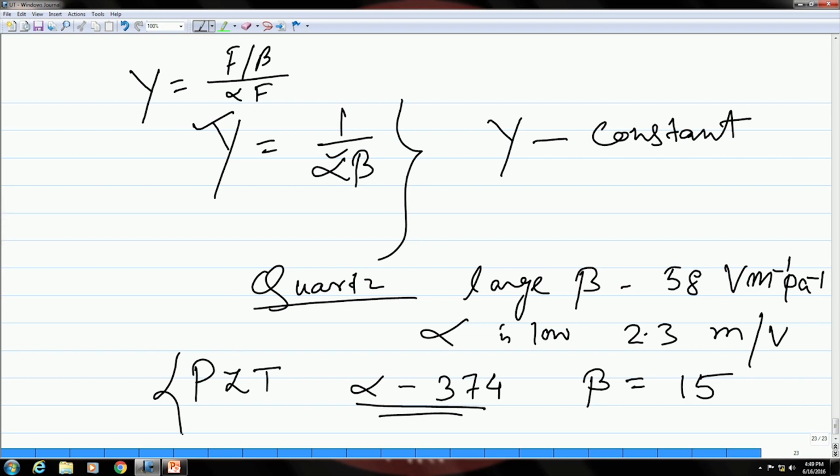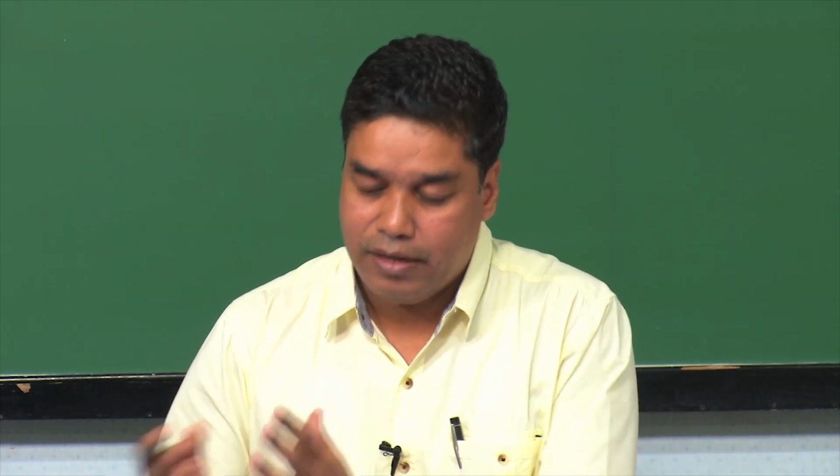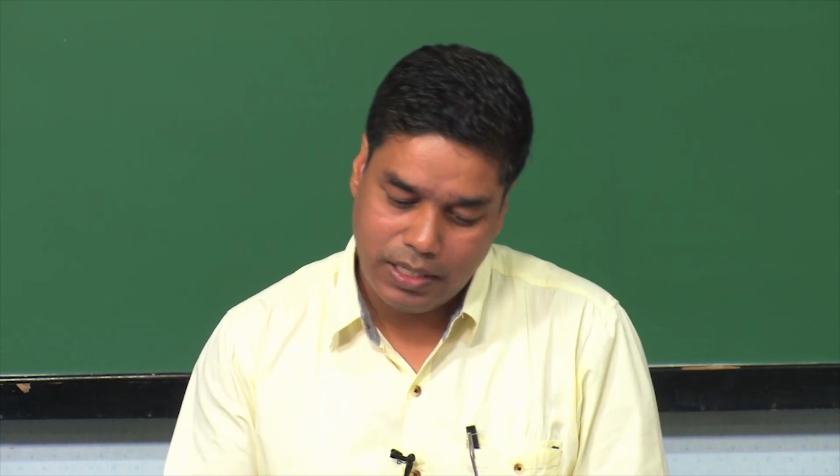But quartz also can be used, because we are mostly concerned about receiving the signal which is coming out from the sample in terms of those echoes coming back from the defects. So, if you have a good receiver, and if you could ensure that you send enough ultrasonic pulses into the sample, then quartz also is a good material.